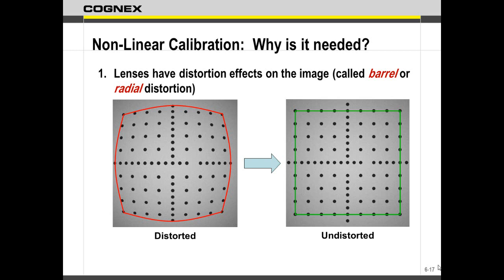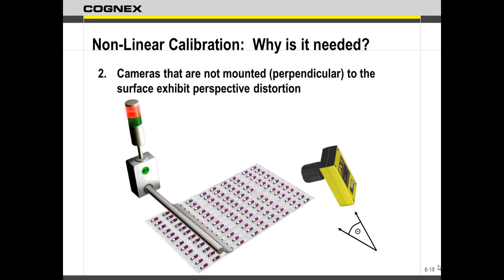That's great, except that's not very accurate. It's only going to be accurate right at that area where you actually did the measurement. As you start going around the field of view, it could be thrown off. This could be because you have lens distortion, and the lens distortion can come from not having the correct lens matched up with your CCD or just using a poor quality lens. As you start getting towards the edge of it, it starts taking on a fisheye look. So things look like they're actually starting to pull away.